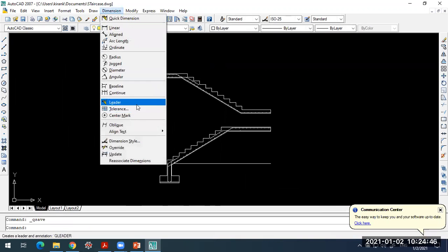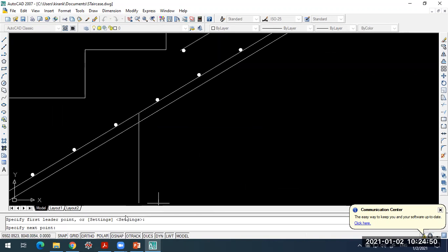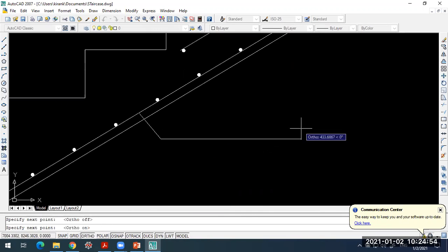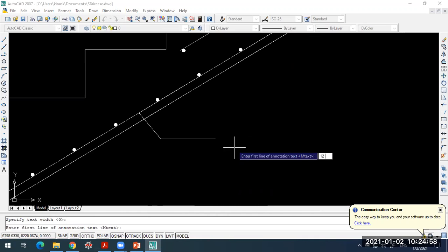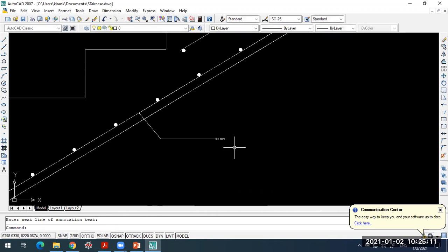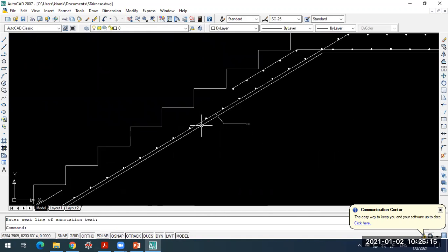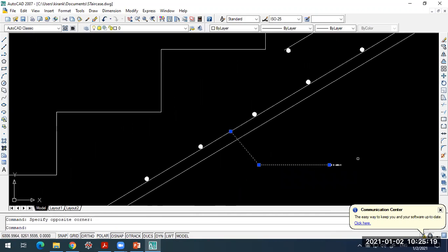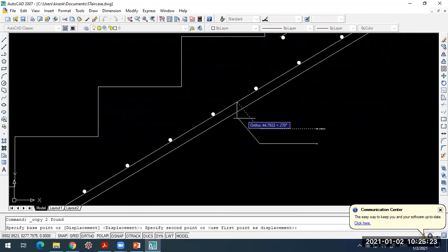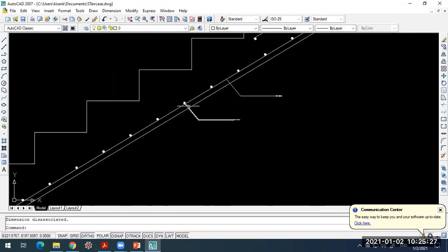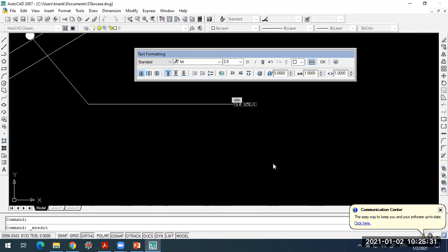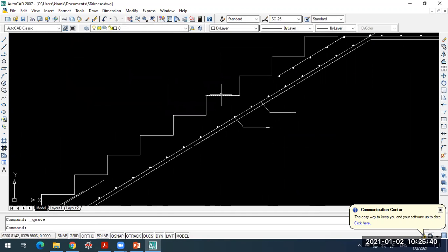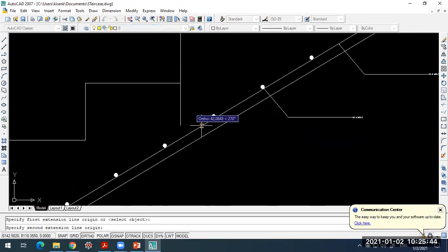So one more thing that is required is detailing. So I choose this one, and this is my main reinforcement, which is 12. Let's keep it Y12 at 125 center to center. Okay, this font size can be increased. Okay, and distribution steel what we have, just copy this one itself. This is the distribution steel. So for this it is 10. Okay, it is just required to change the font size and dimensioning base slab thickness.